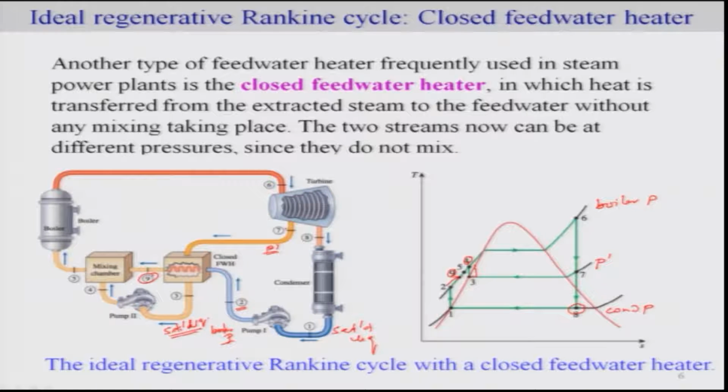Now it is being mixed. So, this is your mixing chamber. Okay. So, it is being mixed. Of course, the average temperature will be less. So, the final outstream will have a lesser temperature than 4, which is your 5. 5 is the stream at this temperature that goes to the boiler. Okay. And it should be noted that 4, 9, and 5 all have the same pressure. So, it is constant pressure mixing. Okay. And that is why the 5 is there.